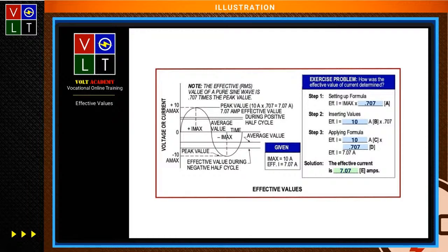Now, when I look at determining the effective value of an alternating electromotive force, this can be determined by multiplying 0.707 by the maximum EMF. So when I look at all that and the calculation and apply it here, let's just pull out the values.